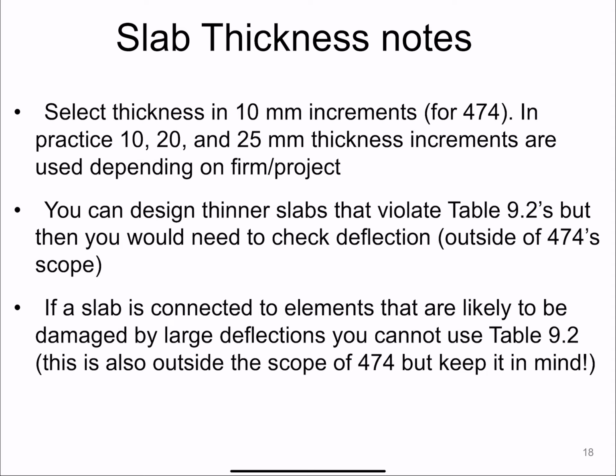The code only says that you don't have to worry about them; they wouldn't compromise the safety of it, but you would have deflection. So you'll have to keep that in mind. If you want to absolutely limit your deflections because you have sensitive equipment connected to your one-way slab, then you definitely need to use a different method.